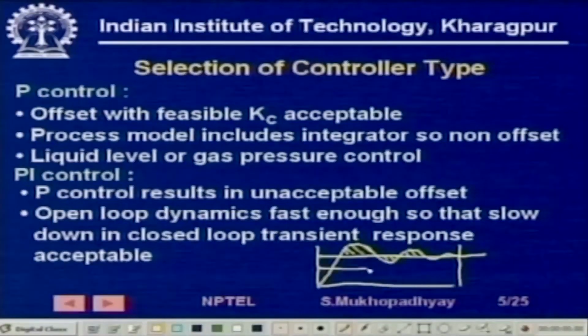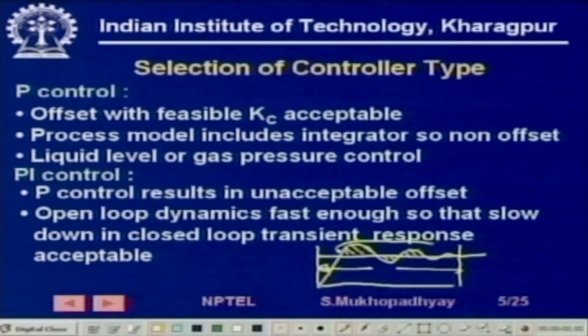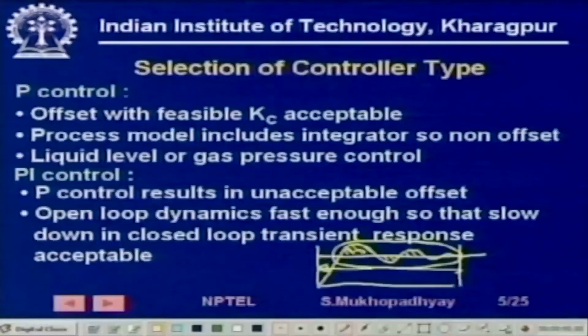So if this interval over which there is some error is small compared to the frequency of set point changes, then you can say that even if during this period I have some error and my control performance is maybe affected, with an integral error criterion it will be less affected, because this positive error is going to cancel this negative error. Even then I am able to tolerate this much error, because it is going to die down reasonably fast, and then it will stay on for a long time.